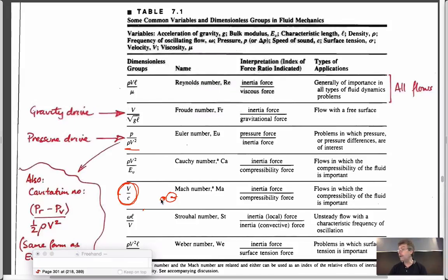So this is how far the energy would have traveled for the first ripple if it was physically moving through the system. So you end up with a Mach cone, which is centered on the tip of the aircraft, which was here at some earlier time, now is here at the current time. And inside this Mach cone, all of the energy that you're generating to push yourself through the air is being trapped in here. So you have to make flight structures that are much stronger.